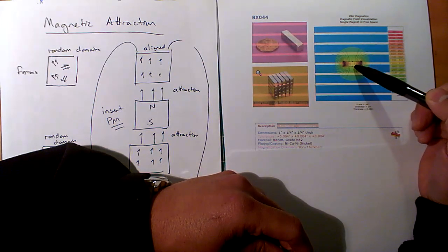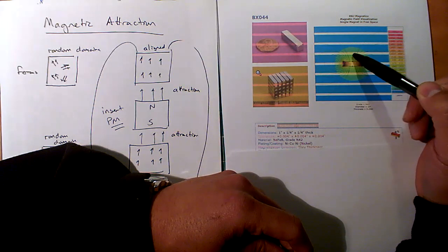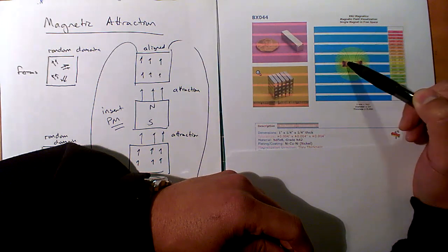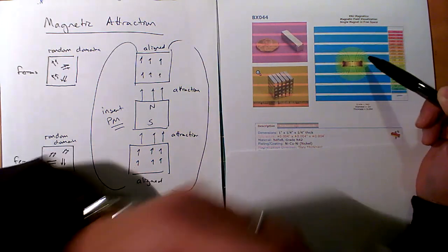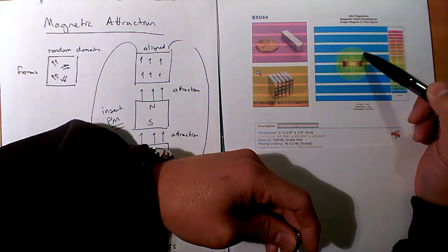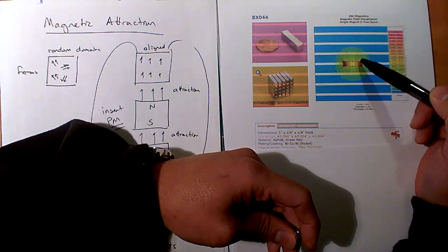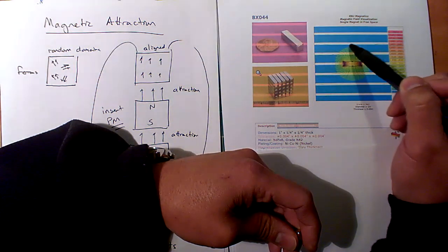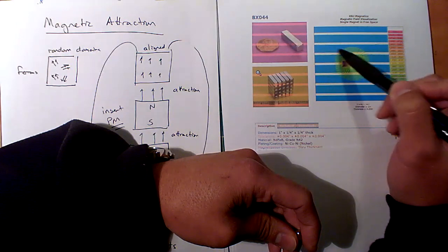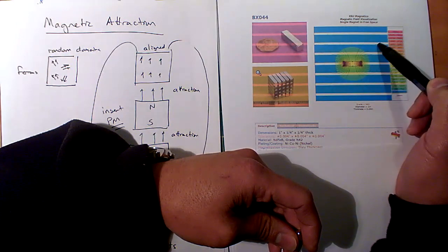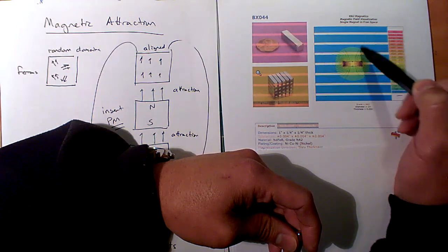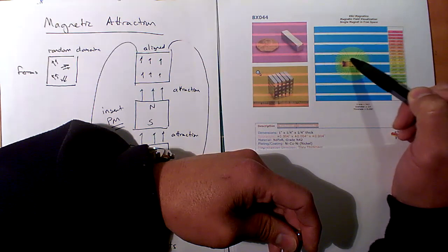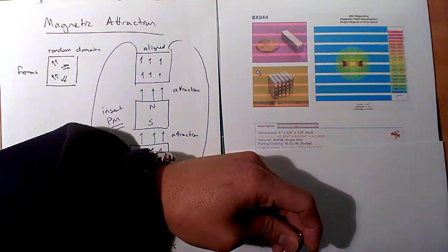The other thing I want you to note is it's not uniform. Look how, yes, sure, right above, it's kind of perpendicular to the surface, but it starts bleeding to the left and to the right very quickly. So these are things you want to account for in your design of your structure, right? You want to think, well, if I have coils way over here or way over here, it's not going to do anything, right? First of all, the alignment is weird and the intensity is low. So this is just all sorts of bad news over here, right? You want to get your coils in this area as close as possible, okay?